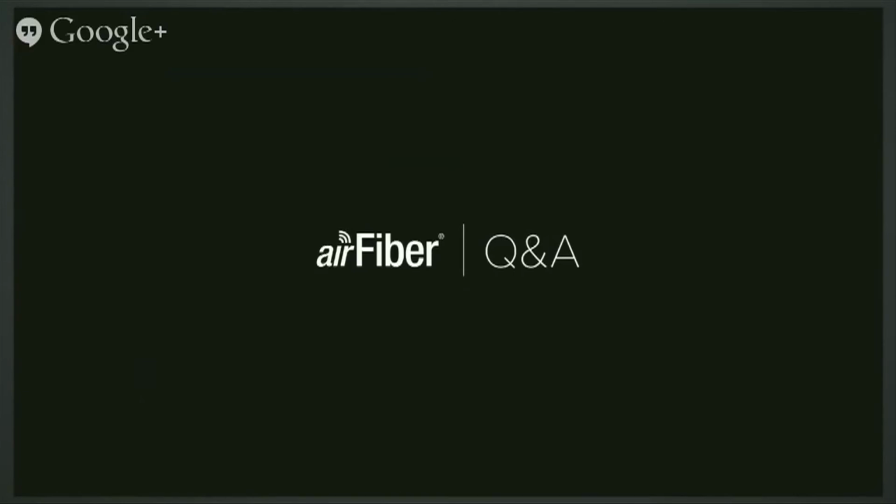What about performance in heavy rain or fog? What's the difference between 5 gig versus 24? Okay, there is a bit of difference there. The 24 gig spectrum is sensitive to high levels of humidity, which is rain. I don't know that fog really has much of an impact, but rain does. And so if you're in a particularly wet climate, and that's something that you find out by looking at maps that give an idea of how much rainfall you'd expect to see in a given year.